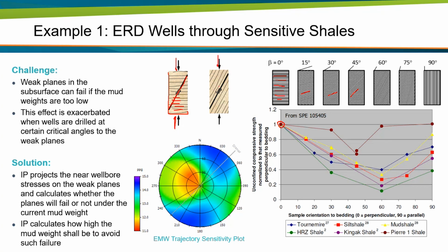And what if these layers are now oriented such that they are very favorable? They are actually, in fact, parallel to the failure plane which will develop. So you can imagine that it's much easier for this sample to slide along that failure plane than this sample over here. So the strength you measure here is expected to be lower than in this case. And indeed, if these layers tilt, you see that the strength decreases for different types of shale.